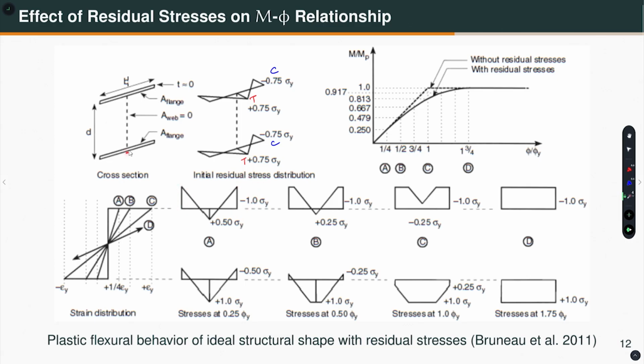What will happen to the bottom fiber? Well, it is under tension. So, it was 0.75 sigma y, you have added 0.25 sigma y because you have applied a curvature of 0.25 epsilon y. So, this will yield, right. Now, if you keep on loading at 1/4 interval, so this is the first point where the first yielding occurs.